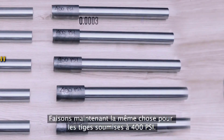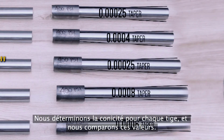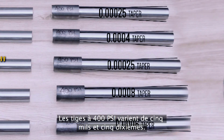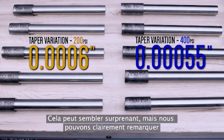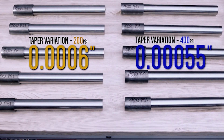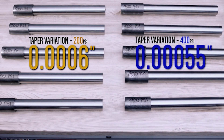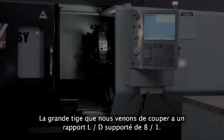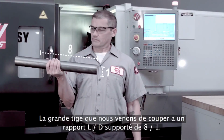Now let's do the same thing for the 400 psi shafts. We find the taper for each shaft and compare these values. The 400 psi shafts vary by 5.5/10. Maybe this seems surprising, but we can clearly see that more tailstock pressure did not make the shaft profiles any more consistent. The large shaft that we just cut had a supported L to D of 8:1.